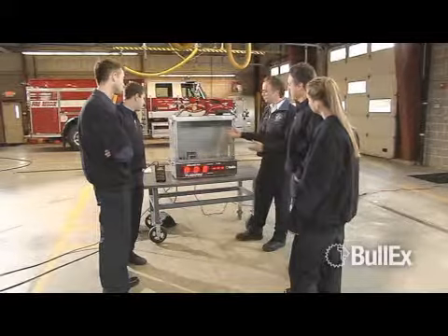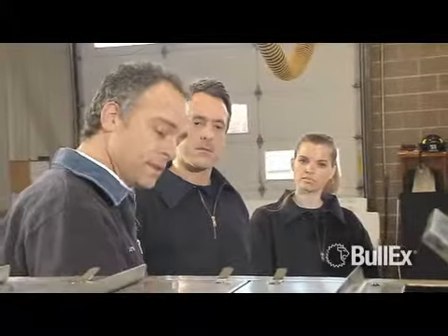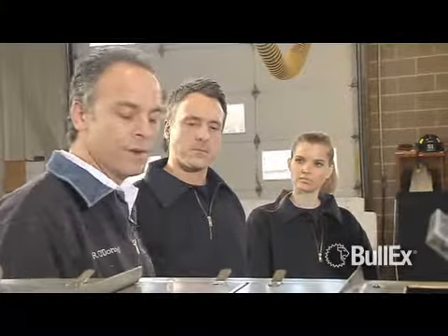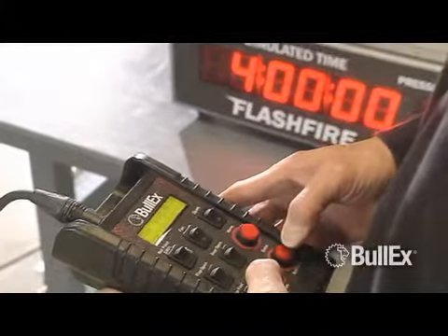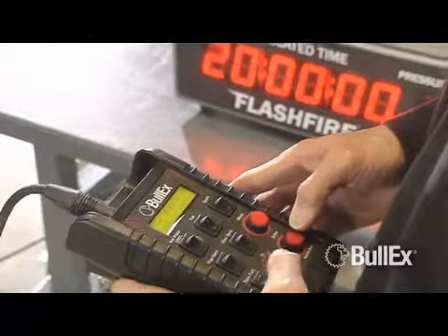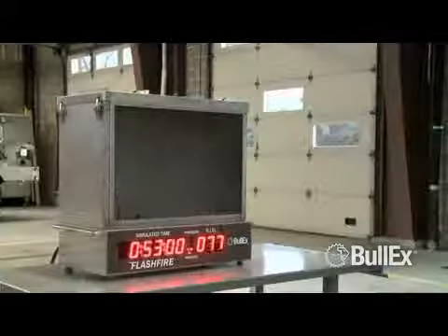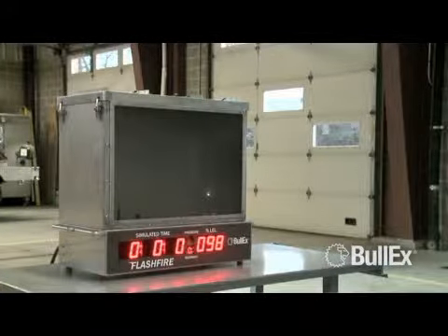Expose your trainees to the explosive potential of a gas leak inside a building when 100% LEL is reached. The gas valve is scaled to reflect a standard gas line's output. Choose from a hot point or electric spark ignition source. The timer is scaled to simulate the amount of time needed to reach a similar gas concentration in an average residential structure. Trainees can watch the emergency unfold as the chamber rises to 100% LEL.